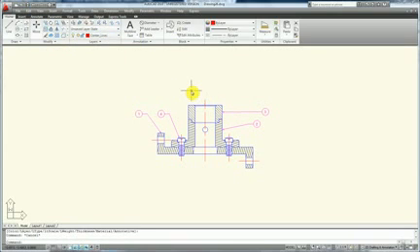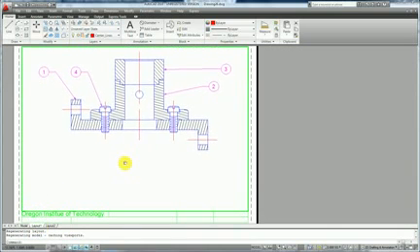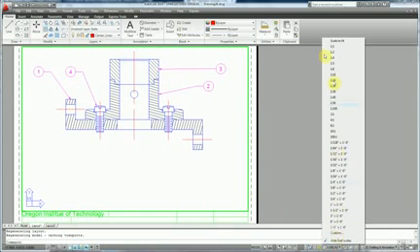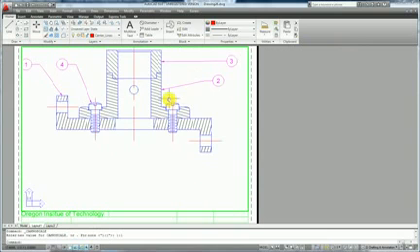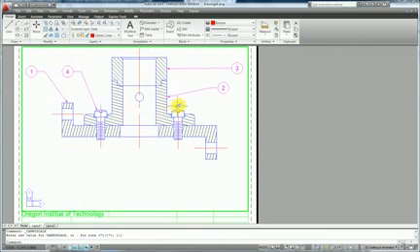Once we've done that, we want to go to our layout, and we want to place our drawing in here. Before we make too many adjustments, we want to change our scale to 1:1, so it's the right size. I'm going to tuck it up in as tight as I can around these edges so that my table will still fit. And now we want to create our table.